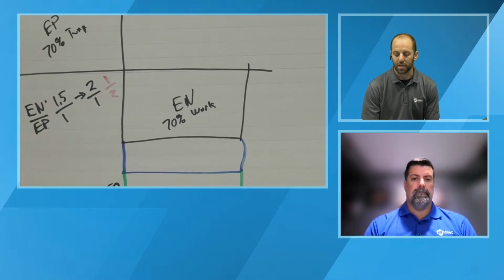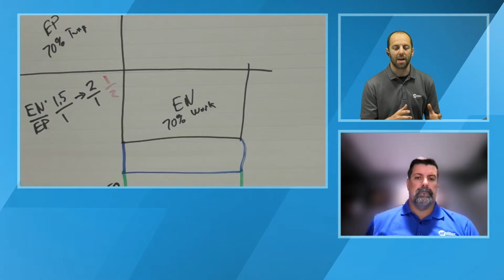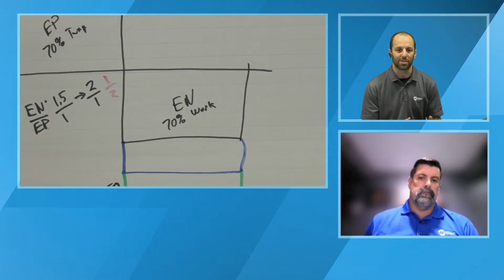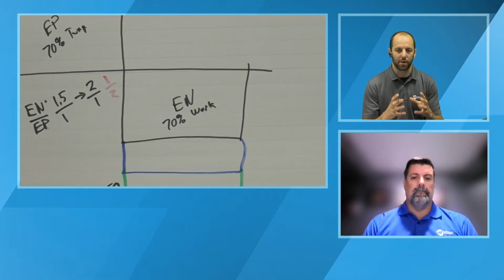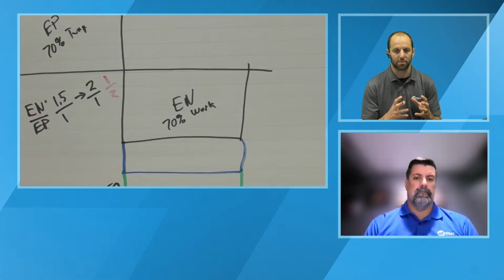That would be used, for example, if you're doing heavy overlay applications or outside corners on thicker materials, where you're going to be using a high amperage and you want a fairly large thermal mass to prevent the tungsten from eroding and transferring microparticles into the actual welding pool.